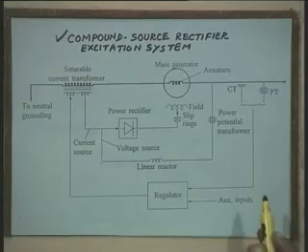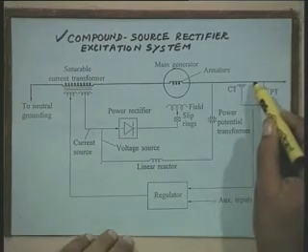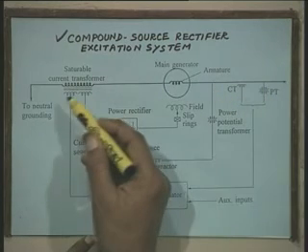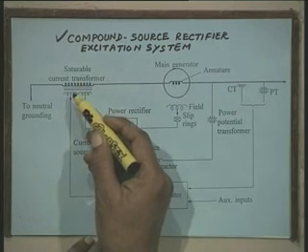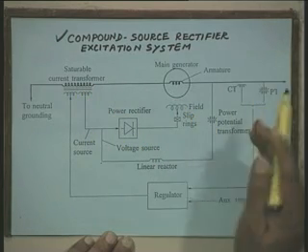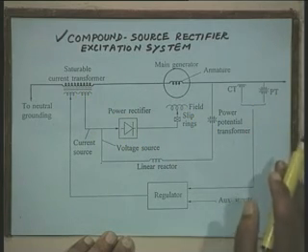Now, in this arrangement, when the voltage at the terminal of the synchronous generator dips, simultaneously the current becomes high. So, we will be in a position to maintain the field current even under disturbance conditions.